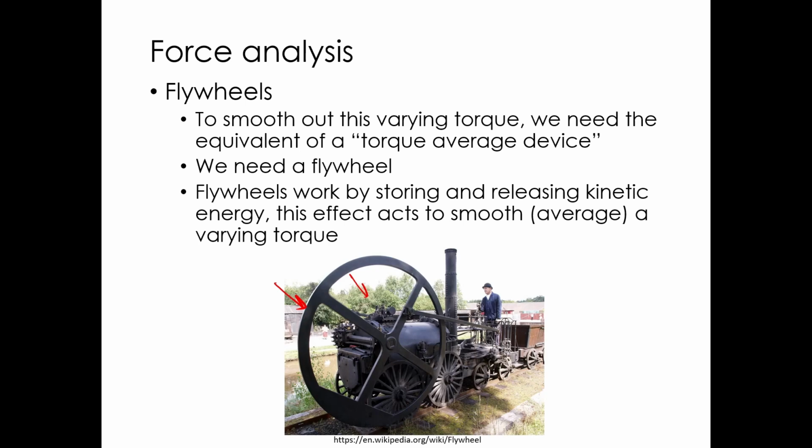So what would happen if you didn't have this flywheel? If the engine would run at all, it would be super jerky. And in some cases, if it has no flywheel, an engine just won't run. It's not able to store energy to get through compression on a 4-cycle engine or a two-stroke engine. You got to have some energy stored up to get through compression. On a single-cylinder engine, where you've got a power stroke, you got an intake, compression, power, exhaust.